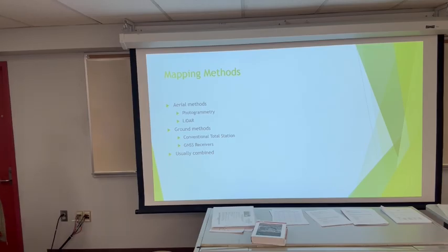Typically, the way that would be combined would be starting off with ground methods, establishing control. If you are going to use aerial methods in this process, you need to have control points that are visible in order to properly georeference the imagery or the LiDAR data, properly have it georeferenced correctly where it is in the world, the proper orientation, as well as setting it to the correct elevation.